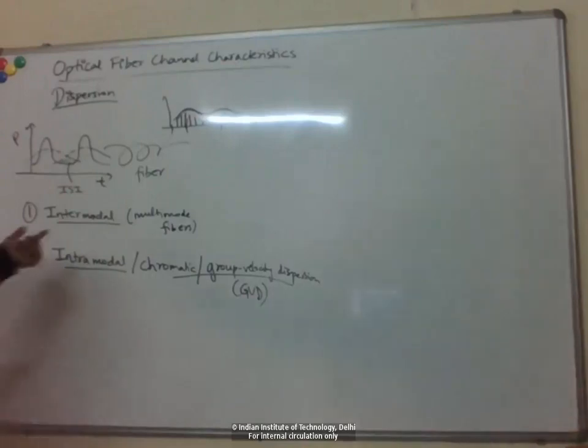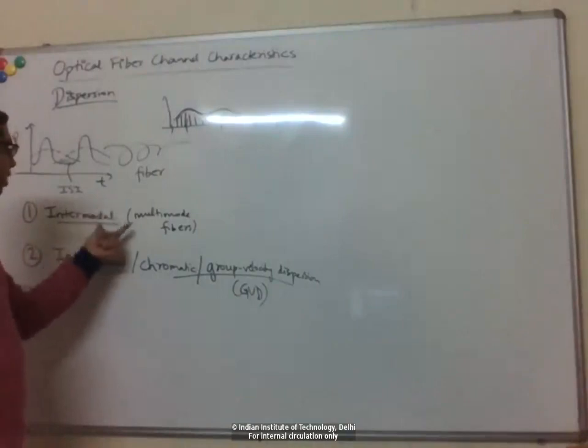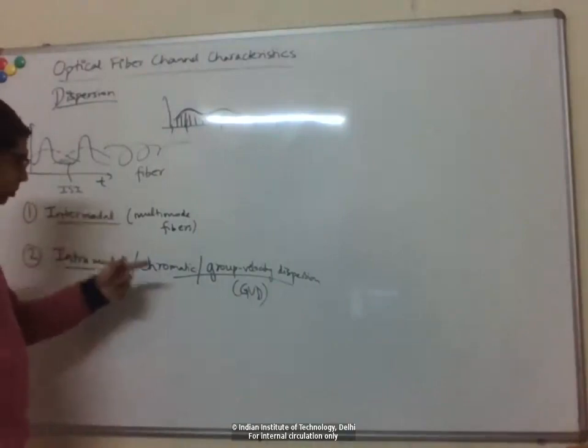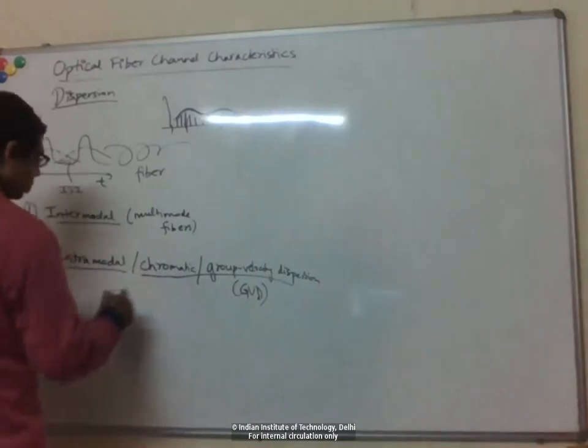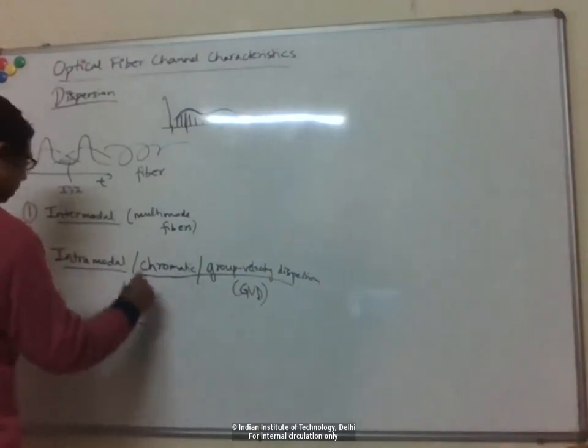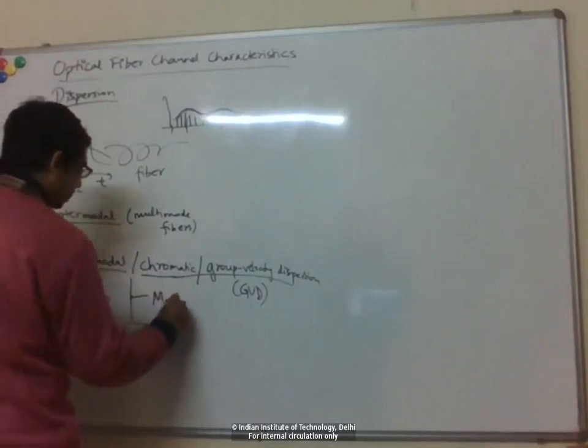Okay, but the magnitude of this intermodal is much bigger than the intramodal. Right? So for multimode fibers, this is dominant. And again, for those who've done the fiber optics course, this again has two contributions. One is from the material,